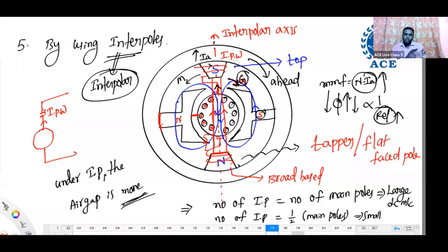Now, if you want to give the statement for a motor, you need to identify. See here, the motor will rotate in the anti-clockwise direction, meaning the rotor will rotate anti-clockwise like this. So the polarity of the interpole is the same as the main pole which is behind this interpole in motor direction. The motor is anti-clockwise. Now to this interpole, which main pole is behind? Behind means backside. South is there, because the rotor is rotating anti-clockwise, in the motor case. Okay, these two statements you have to remember.